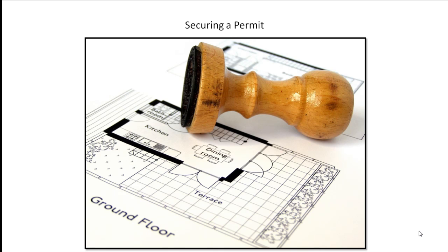Applications generally require a site map drawn to scale that indicates property lines, streets, and the proposed location of the array. This simple drawing should also indicate the location of other components of the system, for example, the inverter, disconnects, and electric meter in grid connected systems. A professional installer will prepare a site map for you. It's a part of his or her service.